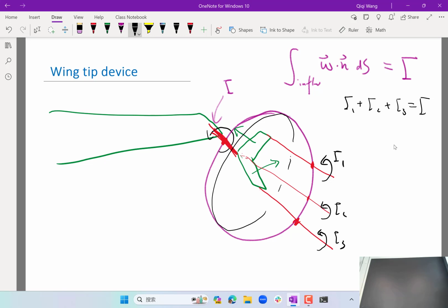So what is the difference then between putting the winglet behind or on the wingtip? From the downstream flow point of view, there is not much difference. The difference is from a structural loading perspective, in the sense that if you put the winglet behind, you are spreading out the forces.